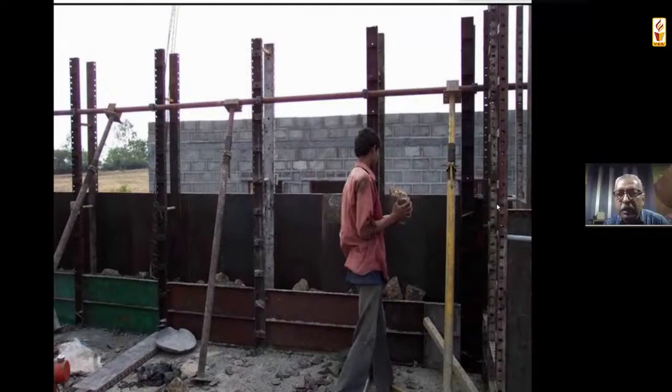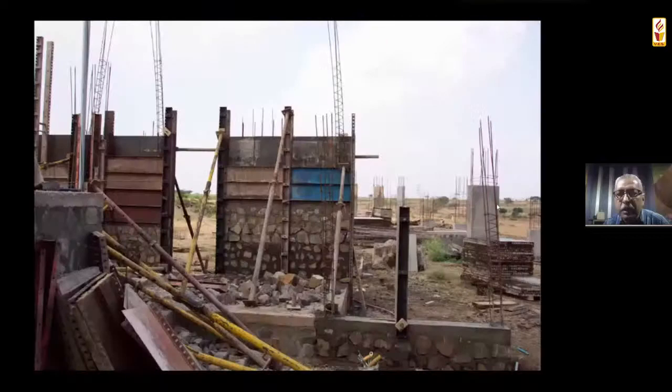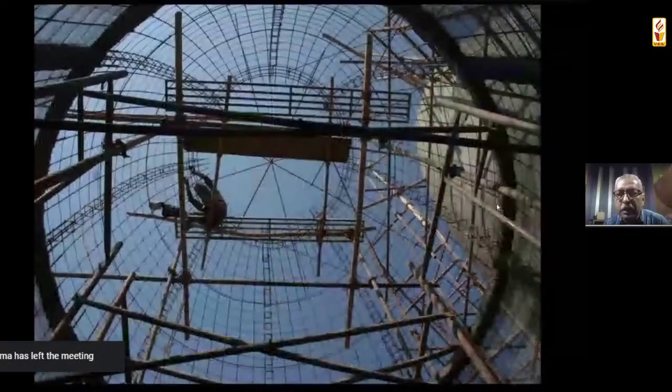So you take, this is in Ahmednagar, and a lot of stone was available because their land bank was almost 100 acre. So what we did, first we collected all the stone which were lying here and there, and to a particular size we cut it, and then with simple labor we started pouring in that. And once that 600 mm height is achieved, we used to pour concrete into that, where cement ratio was very less. And then you get this very strong load bearing 200 mm thick wall, and from inside you can just paint it, or even just wash it with pressure water, and it will give you very good results. This is for Narendra Dengre.